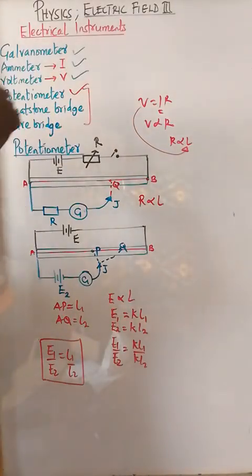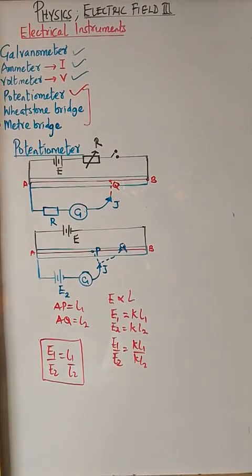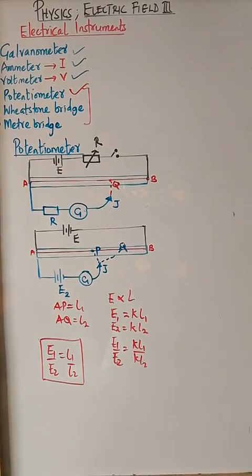So potentiometer is better in measuring PD across a conductor compared to a voltmeter, because it is used to measure the PD when it's driving no current. So if you use this method, it gives us the actual value, unlike the voltmeter. So you have to understand the diagram very well for other purposes.